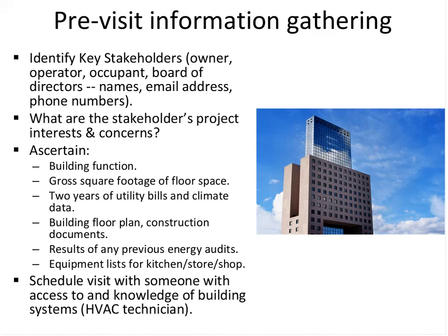Certainly the size of the building, and you'd like to get about 2 years of utility bills, all the energy bills, and then some climate data, basically heating degree days and cooling degree days for those 2 years. So you can match these together and look at the building over time. If available, certainly a floor plan and construction documents. And if they've had any previous audits, you'd like to gather that information. And if it has process loads in the building, certainly gather information on the equipment that is in the building.